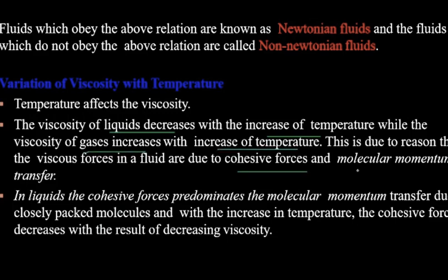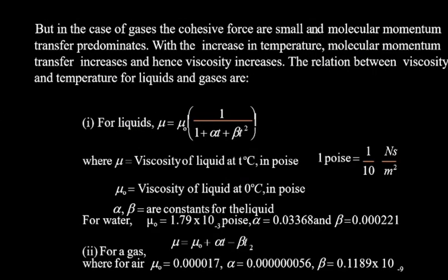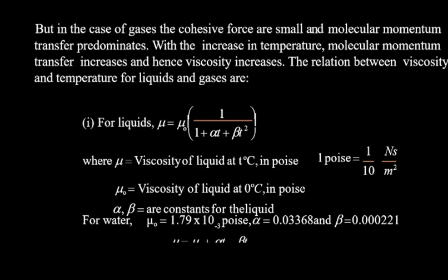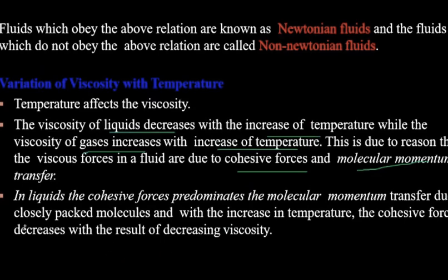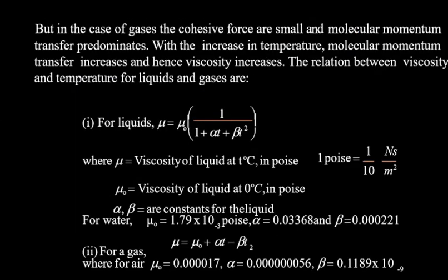Because of cohesive force and molecular momentum transfer. In liquids the molecules are closely packed and the cohesive force is strong, but in gases the cohesive forces are small and the molecular momentum transfer predominates. With the increase in temperature, the molecular momentum transfer increases, and hence viscosity also increases in gases.